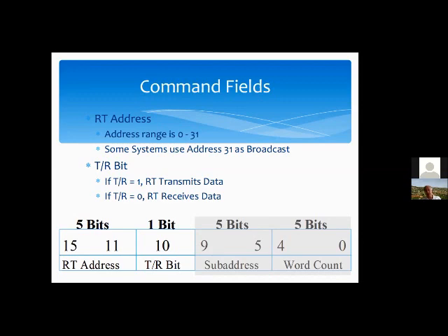On many RTs, there are straps on the RT which let you set the RT number. Because the manufacturer doesn't want to set it because he wants to sell it to a whole bunch of different planes, and each plane may need it to be a different number. So he'll put dip switches or something like that, jumpers, and the user can determine which RT address he wants.